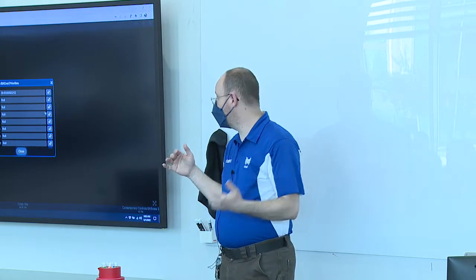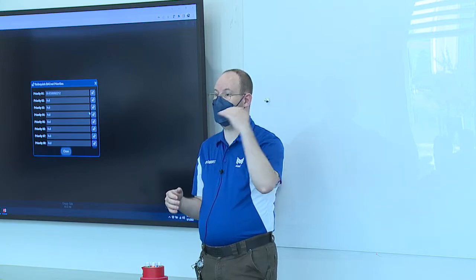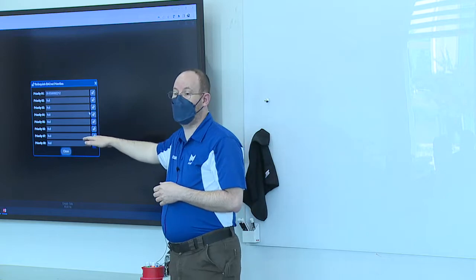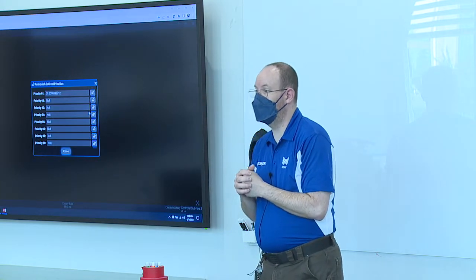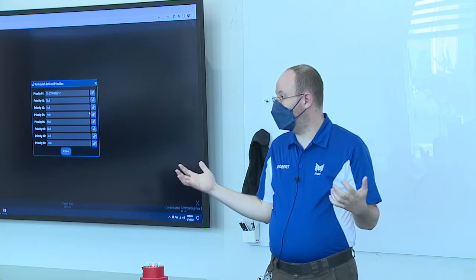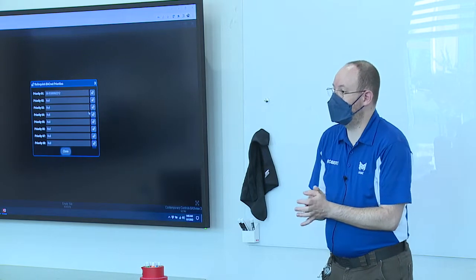Priority 10 is a normal operating priority. So most of the time, if you have something like a reset schedule controlled set point, let's say a discharge air temperature that's reset between 55 and 65, you would bring that in on priority 10. Because priority 8 is your operator override level, a standard level where we let our operators change things.